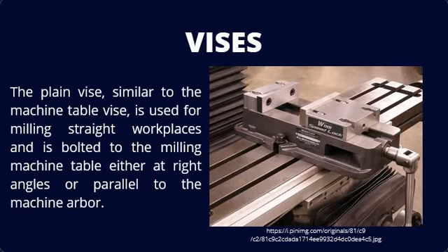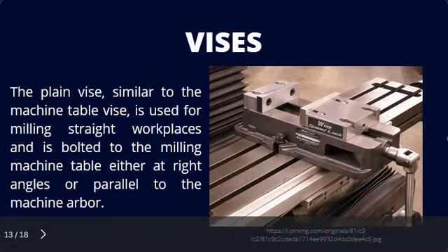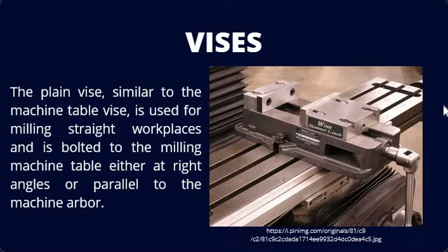This machine vise is a mechanical device designed to hold workpieces still during machine operation. The vise can securely fasten castings, forgings, and rough surfaced workpieces. The jaw can be positioned in any notch on the two bars to accommodate different shapes and sizes. This is used for clamping the workpiece.